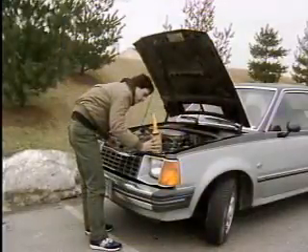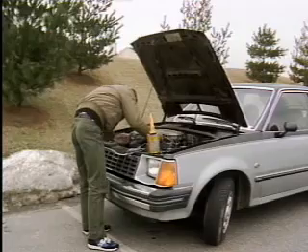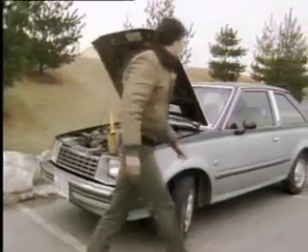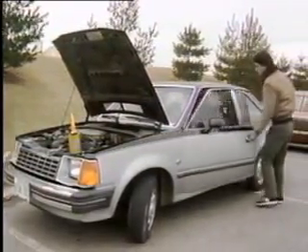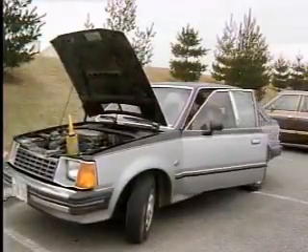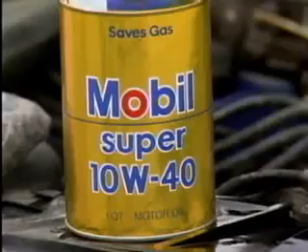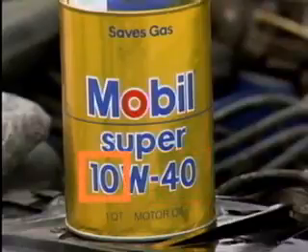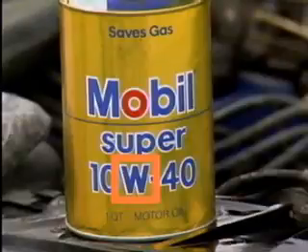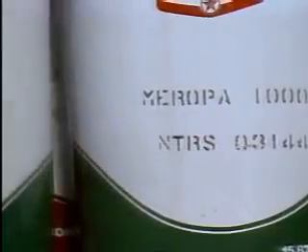For that reason, many oils today are multi-weight. They combine the properties of a lower viscosity oil for low temperatures with those of a higher viscosity oil for high temperatures. A common example is 10W40 oil. At higher temperatures, it will have the properties of a 40-weight oil, and at lower temperatures, it will have the properties of a 10-weight oil. The letter W follows the weight that's associated with lower temperatures. The fact that oil is available in many different viscosities makes it a good lubricant in a wide range of applications.